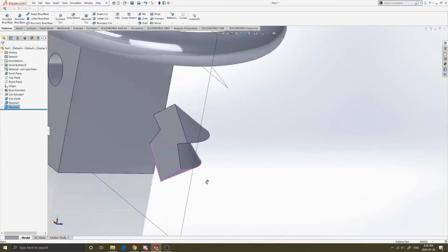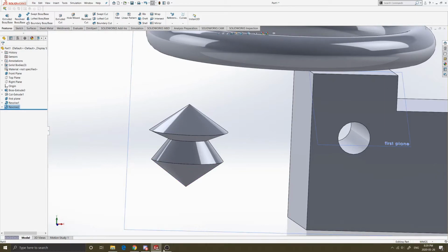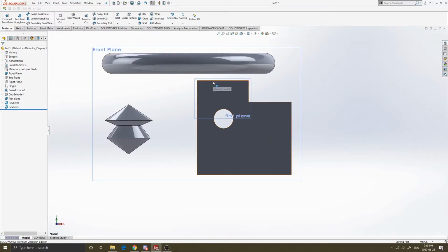And now you have this flat top. So this object here that I made uses the boss extrude and the cut extrude tool. But if you were to make a part, like for example this part, and you always want a hole in it, a good general practice is to reduce the amount of features that you use, or the amount of sketches and so forth.